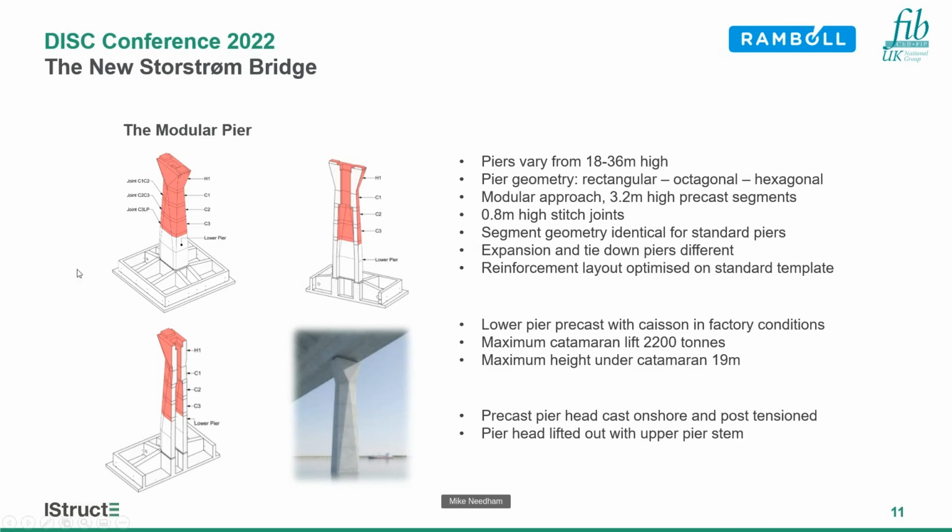Within those precast segments, the reinforcement layout is optimized using a standard template. So there are standard positions for where reinforcement can be placed, and within that, some or all of those slots are used for each pier, but each segment is optimized.